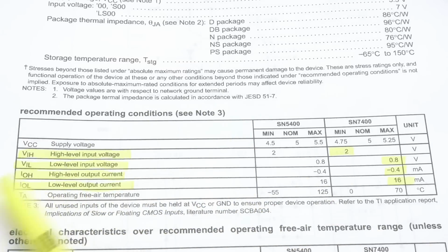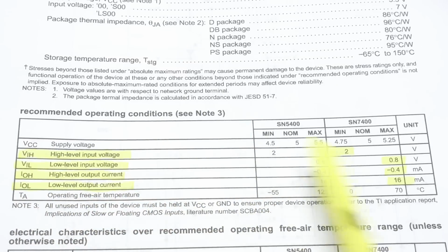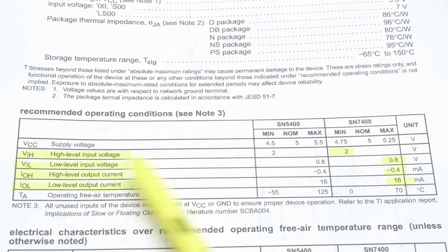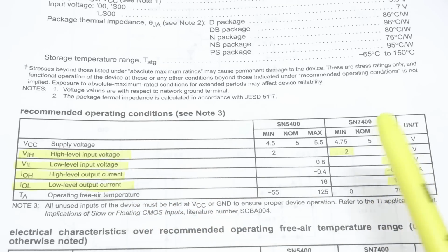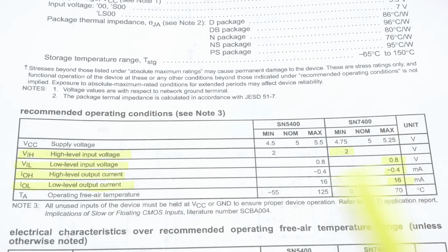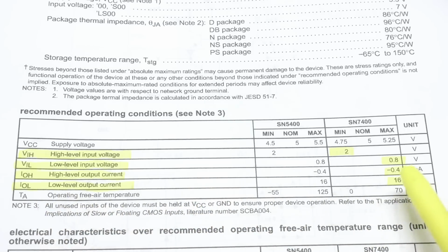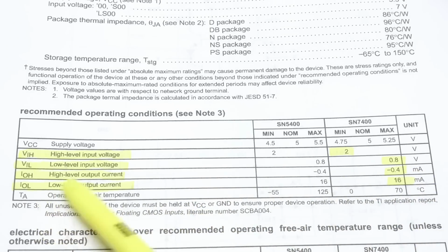All right. This says high level input voltage. There it is, 2 volts. Low level input voltage, 0.8 volts. So you need to be somewhere between 2 volts and 0.8 volts. But look at this. We can drive 16 milliamps low, but driving high, 0.4 milliamps. It just can't pull up very hard. And so that's when you start getting in trouble if you start loading this thing down, called fan out. As you have more and more stuff on this output, you can only supply 0.4 milliamps. And so you just really can't drive much.